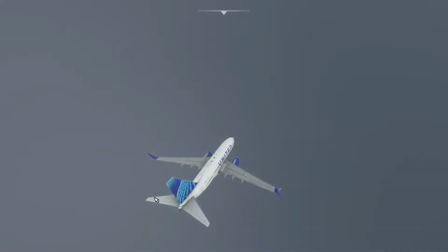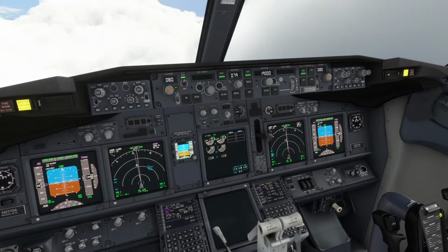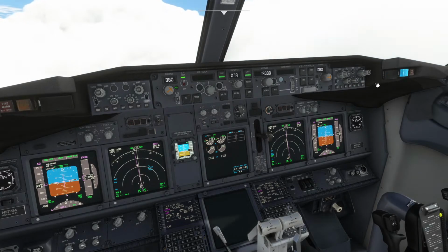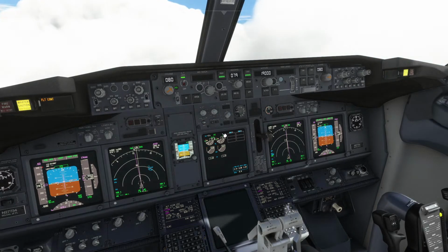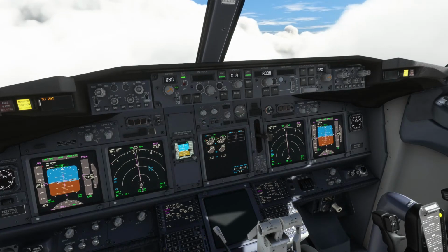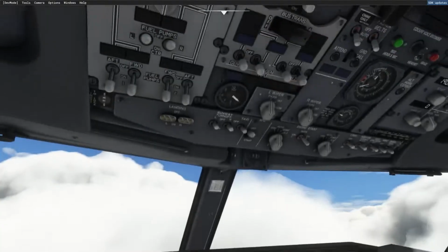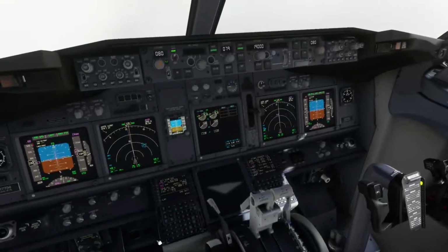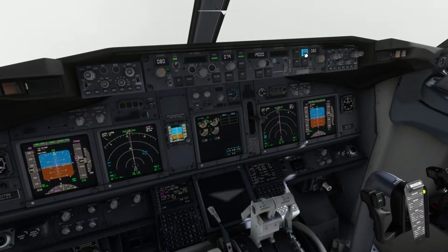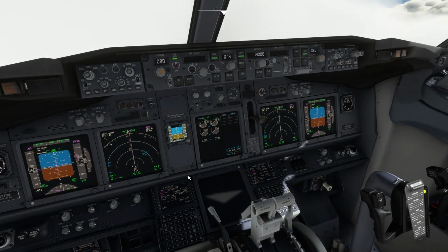Okay, let's see outside. We are getting close to some clouds at destination, and now we have master caution, hydraulic again. Okay, manual flight, I have controls. Flight director, and we have flight controls as well. I'm going to reset this master caution. Flying manually. So yeah, we lost the system A, so we can turn on the command B to keep 190. So command B is there.